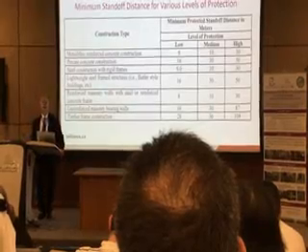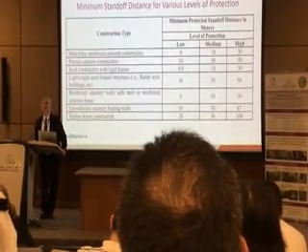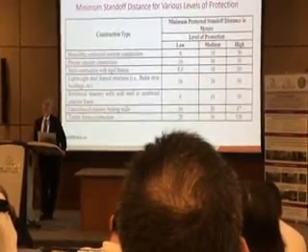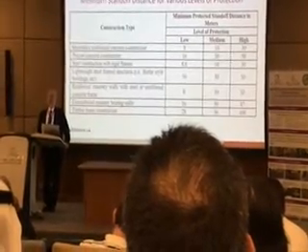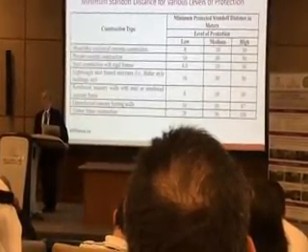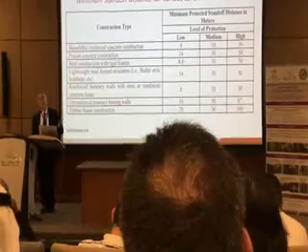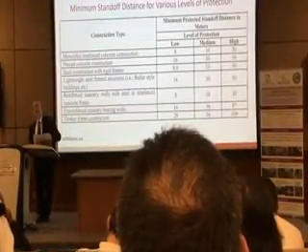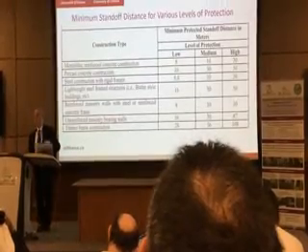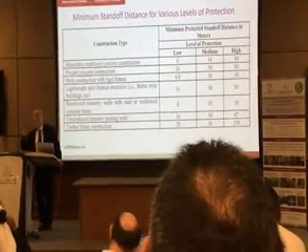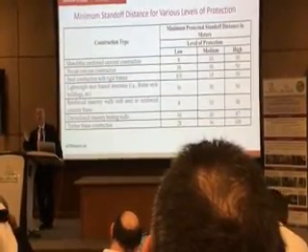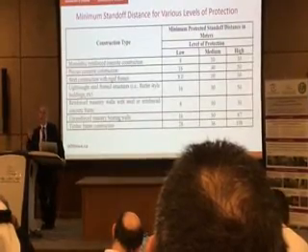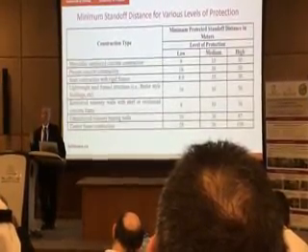When I lecture about this to my students, I give the car example. When you accelerate your car, you lean backward. It's not because somebody is pushing you back; it's the acceleration of the car, and your mass pushes you in the opposite direction of motion. Here, when there is a blast effect, the mass of the building reacts to it. And this helps you. This is inertia force.